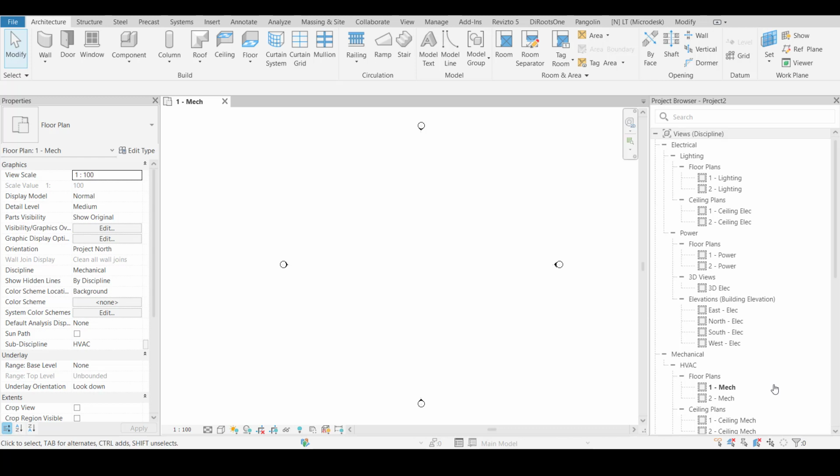Okay, so if you have gone through all those lectures, you might understand very clearly that the contractor comes and takes the IFC drawings which are received from the client but were produced by the consultants. Then they refer to that and produce their shop drawing, and that shop drawing they give back to the consultants for approval. Once the consultants approve, then that drawing goes to the site for the execution purpose. So this is the general way of practice in our current situation wherever the good projects are going on.